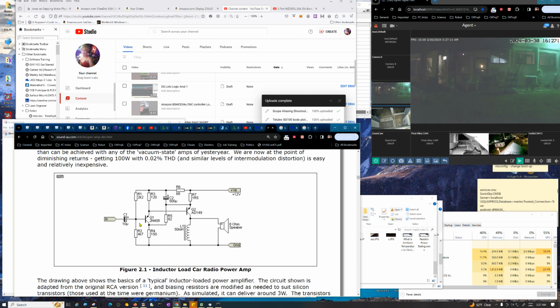You may think, well, that's an AC application, isn't that illegal? Well, the only thing you've got to remember is that it's not illegal to have an electrolytic capacitor with a varying signal on it. But you want to make sure that it always has DC applied, and he's kind of alluding to that in his little capacitor section of that article in the Elliott Sound Products articles. This also is on his site.